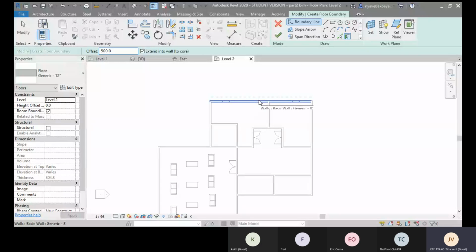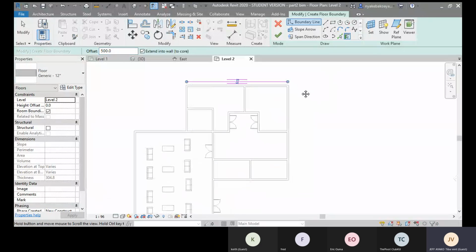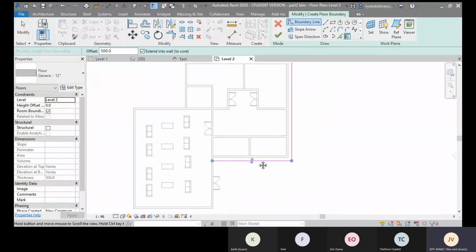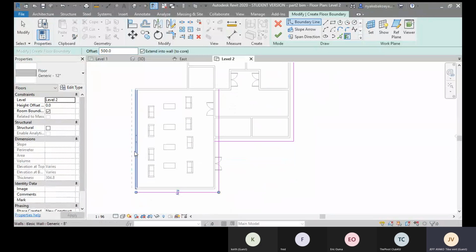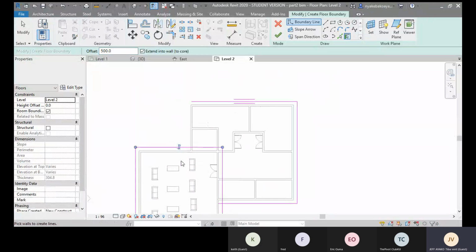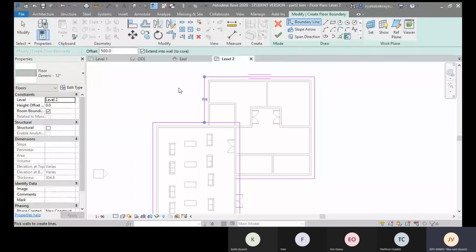the dotted line there, those witness lines. They show you that your floor will be extended outside. So once you click there, it offsets outside. Click that wall there also, like that, like that, like that. It makes your work so much easier. This is why I usually love Revit for some of the projects that they do.